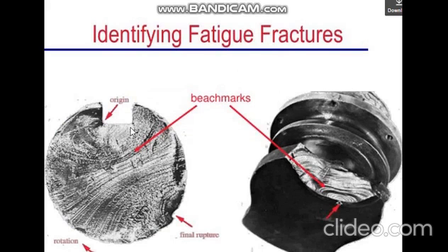You see, this is how you can identify the fractures. Here they showed the origin. This is the origin, that is where the crack was, and slowly it propagated. These are the beach marks you can see. Okay, and finally it fractured. And here also it is shown.